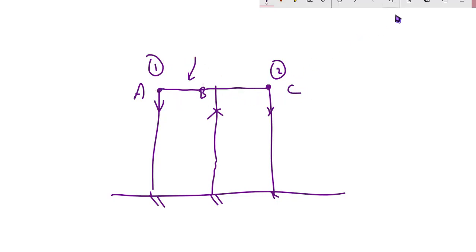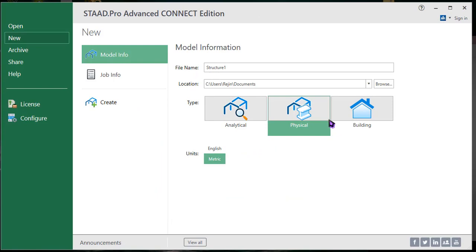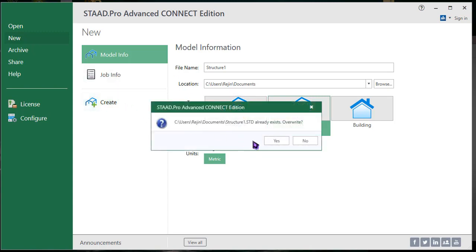So what we want to do here is, while drawing these beams onto the columns, we'll pick the first point and second point on column B, then draw a beam once again and pick the next points, so that we might feel that this won't be a continuous beam, but actually it is. For the proper transference of load, each and every node must be there on the column if we are drawing the beam. So keeping all these things in our mind, I'll be drawing up the physical model. It's the first software ever where we can draw a physical model like this.